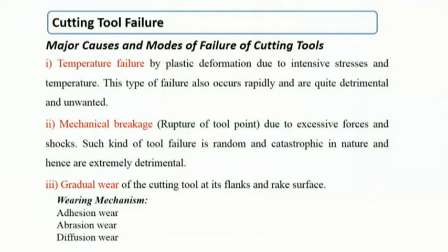The other mode of failure is mechanical failure or mechanical breakage, or we can call it a rupture of the tool point. So basically, when there is relative motion between tool and workpiece, and the cutting forces are high, and the tool material like diamond and cemented carbide is basically brittle in nature.